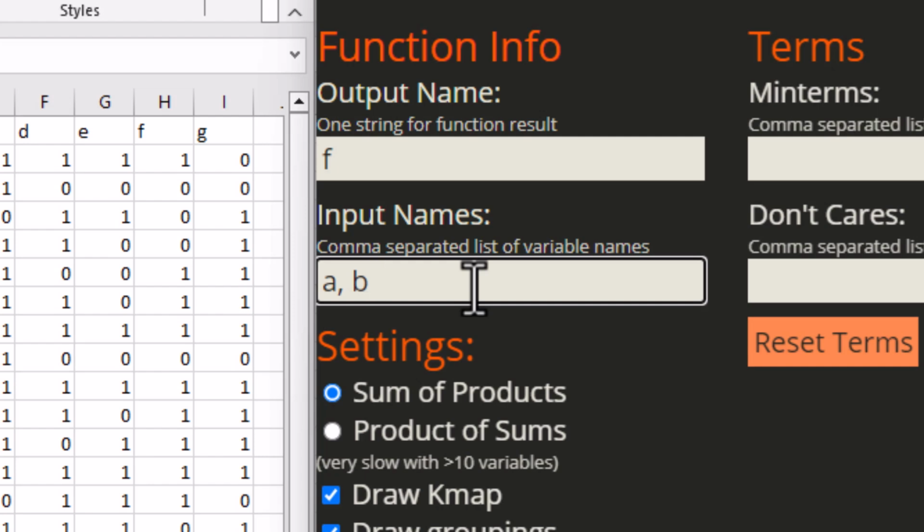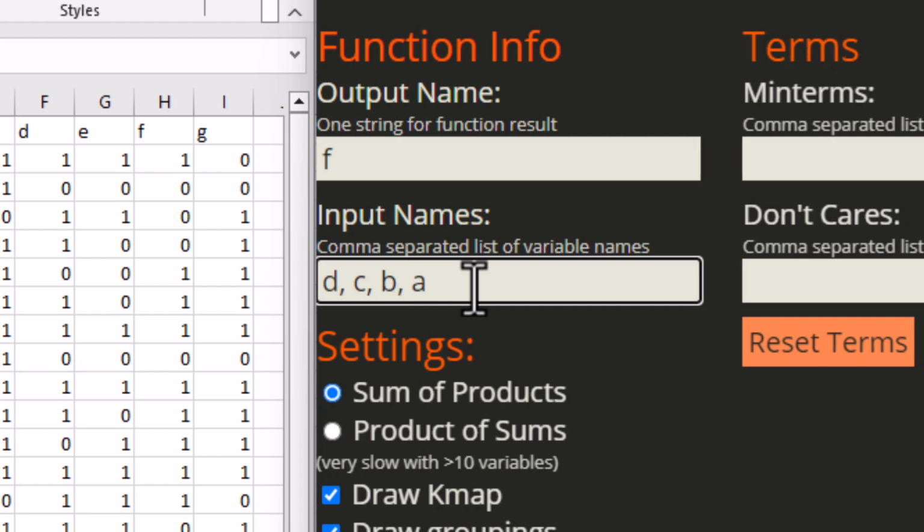My first step is to reorder the inputs D, C, B, A so that they are right to left and match up with the normal visual order of the 4 bits. This is not required as they are only variable labels and can be done in whatever order you find comfortable as long as you use the labels consistently from truth table through coding.